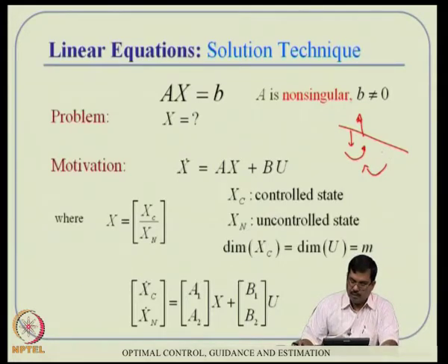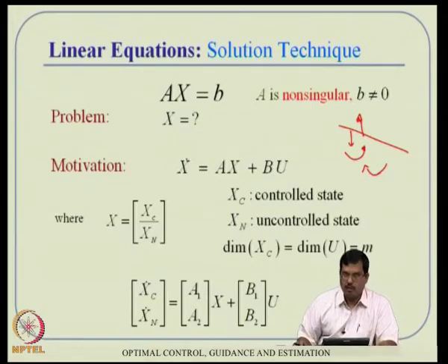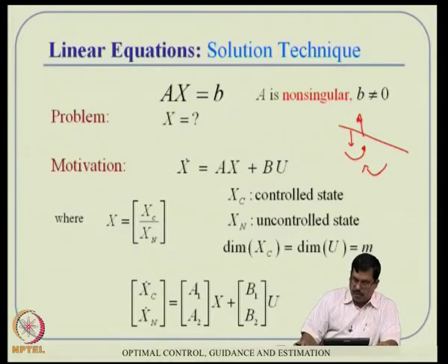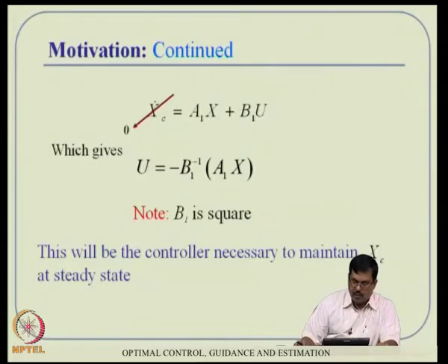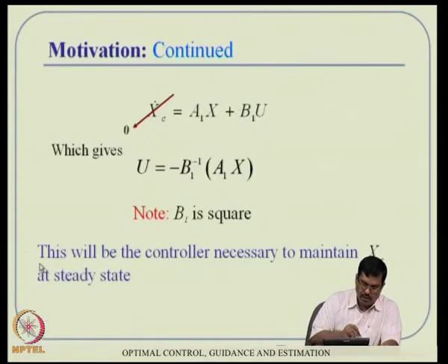So, that trim condition is actually a forced equilibrium point in aircraft flying. Those of you who cannot relate to that, we will see that a little later, or it is very obvious also, it is not too much. You can see this problem from other example problems as well. So, what am I looking at? I am looking at some solution for xc dot equal to 0, that means the control states are operating under steady state.